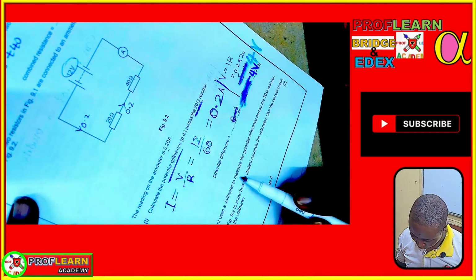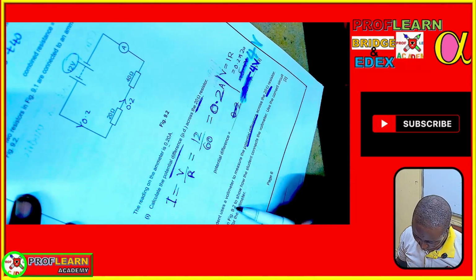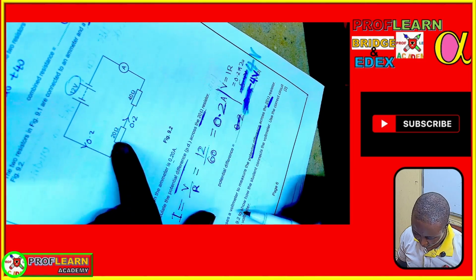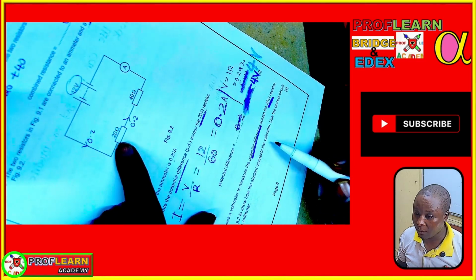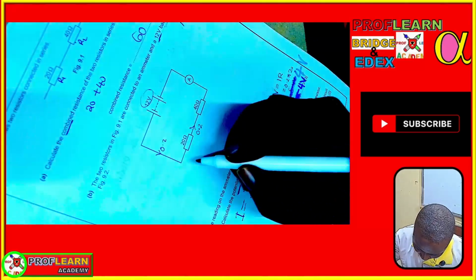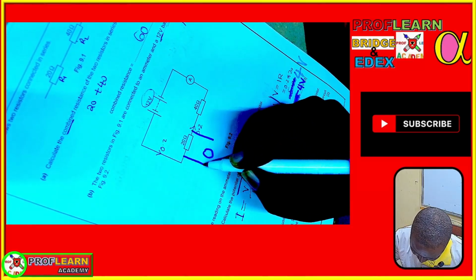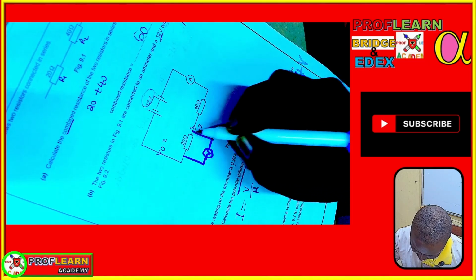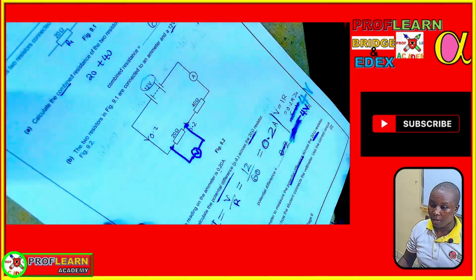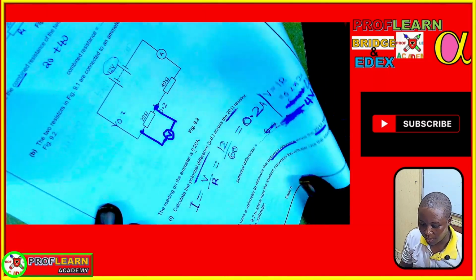A student used a voltmeter to measure the PD across the 20 ohm resistor. Draw on the figure how a voltmeter should be connected. So we are going to say a voltmeter will be connected like that. It should be connected in parallel, because it's a high resistance device.